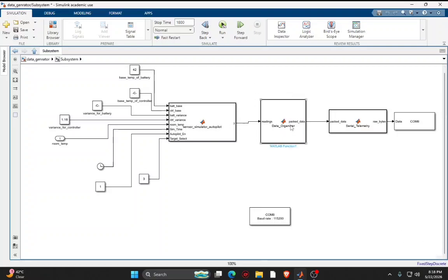function block. After that, that data will get converted into a 16 by 2 vector, and it will be transferred to COM8, where our Raspberry Pi Pico, that is the RP2040 microcontroller, is connected, and all the average calculation will happen on that microcontroller, and we can see the output of that microcontroller on COM3, because the RP2040 has two serial ports for communication to the PC, one for sending and one for receiving.